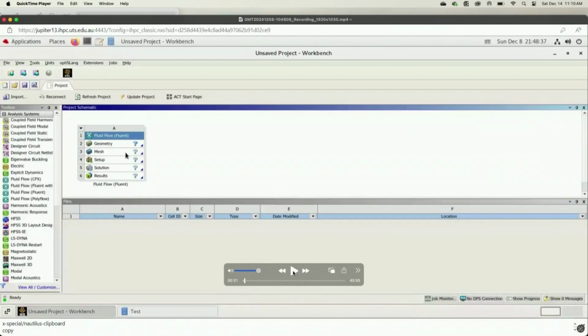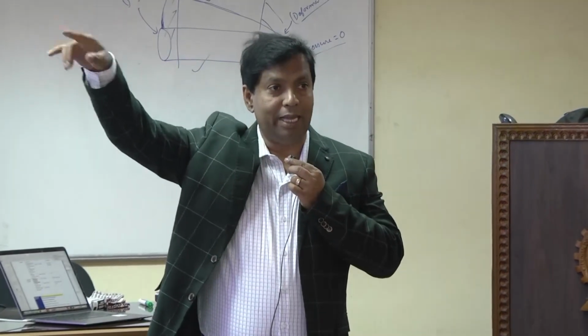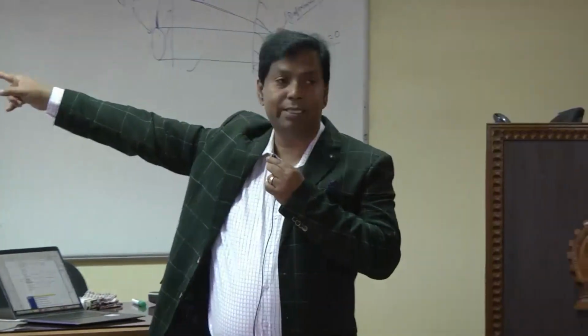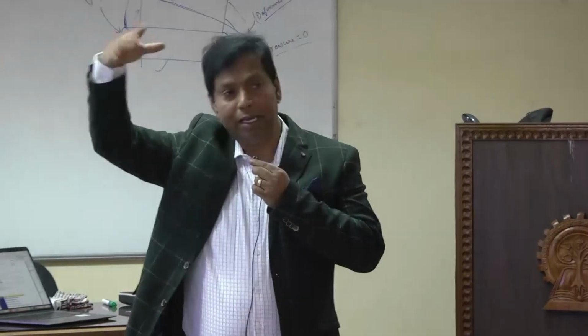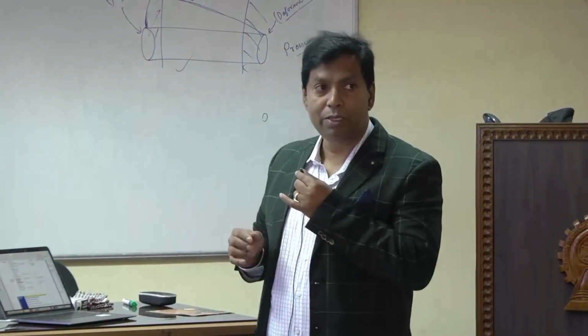This geometry is very simple, like a pipe. Otherwise, we can't show it here like a simulation. I'm asking, once the geometry is created, you have used three or four software packages to create the geometry, but the mesh is done here? Yeah, we just created the geometry with all those software packages, then used Pointwise to create the mesh, and then imported it in Ansys. So meshing is done. You can do the meshing outside. Yeah, not a problem.